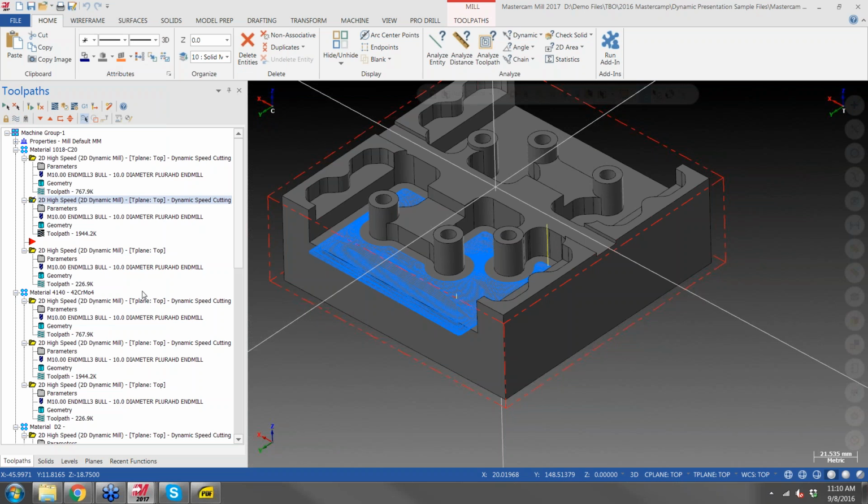As people make progressions in technology, machines went from the old ball screw to servo drive, and the machines, as opposed to being big hoggers of the 80s and even into the 90s, went into being not necessarily as rigid or robust, but the machines can move a lot faster. The rapids got up to really high speeds and things like that. So then the tooling manufacturers caught up with that, and then the software people came out with tool paths that can utilize the speed at which the modern machines can move.